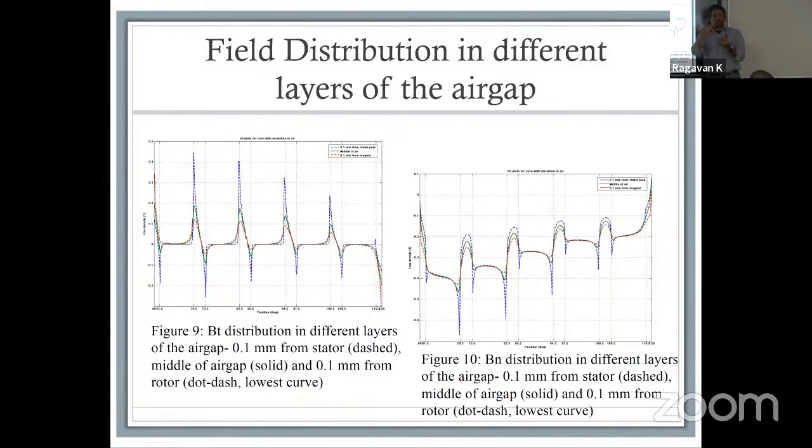So if your flux density is not going to change because you have permanent magnets, that means all you have to do is resimulate your current functions. So recalculate the function, the field that comes from the current, and add that to the permanent magnet flux that has been constant this whole time. That will be time efficient, and it also gives you results for an iterative design that can happen much faster.